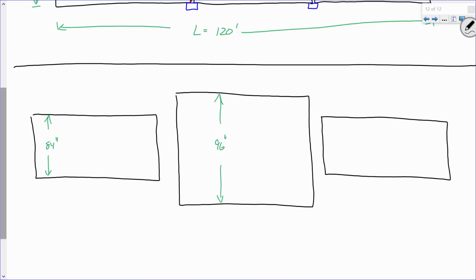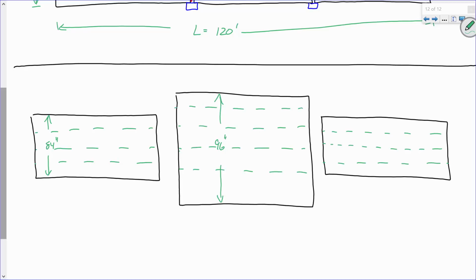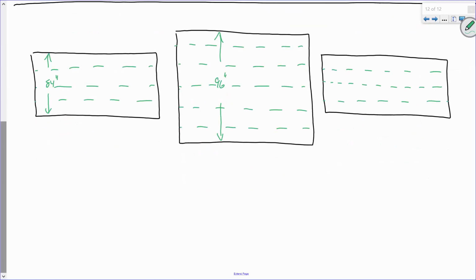So now what you've got to do is right off the bat, you've got to cut, okay? So you got to start off by doing this. And the same thing here. Same thing here. Same thing here. Okay? Then, for each one of those little strips, now you've got how many different strips flying around all over the place? You got 12 different plate strips that you got to manage. That's going to take up space in your fabrication shop. And taking up space in the fabrication shop takes up time and takes up money, okay? That's going to increase the cost.